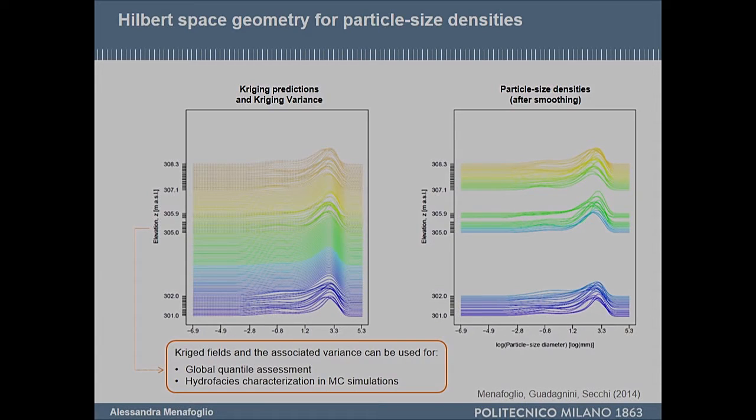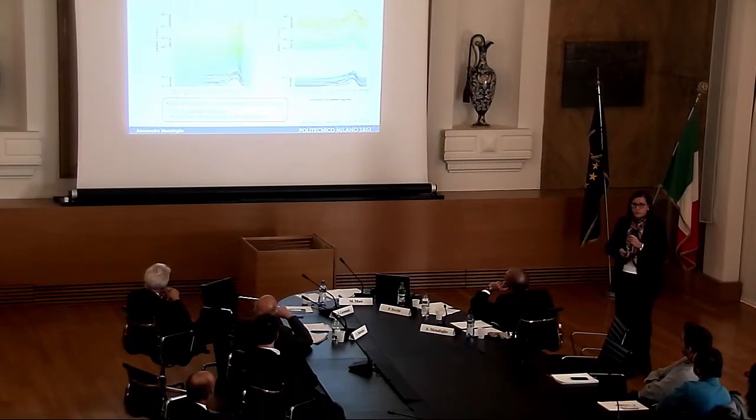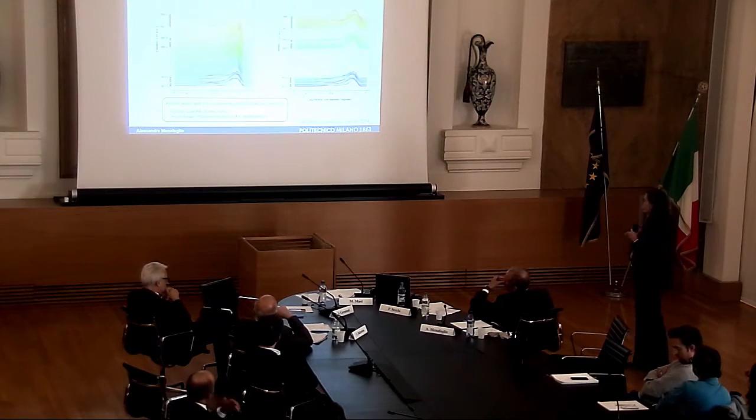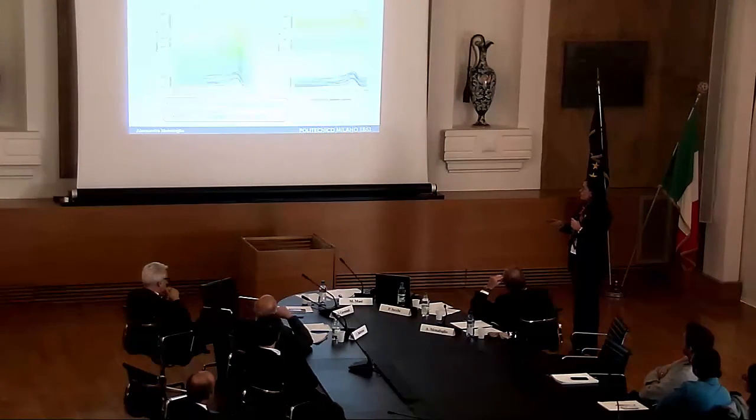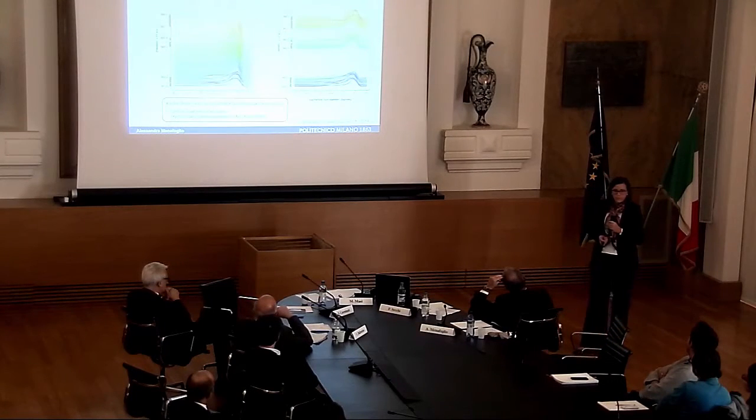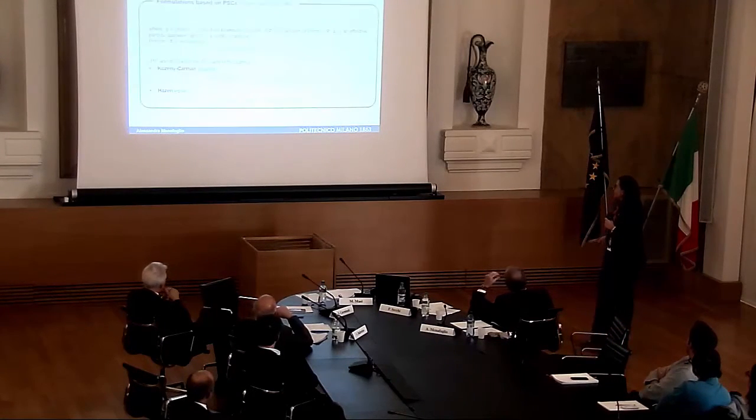They can be used for global quantile assessment, meaning that once we predict the entire distribution function, we are able to predict jointly all the quantiles of the distribution. And they can also be used for hydrofacies characterizations in Monte Carlo simulations.